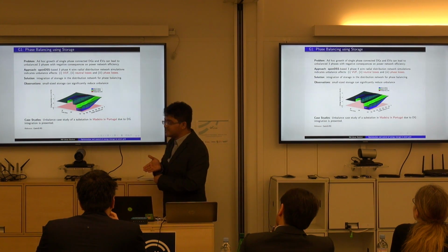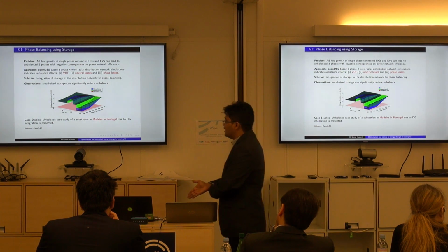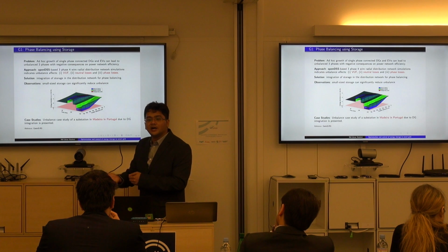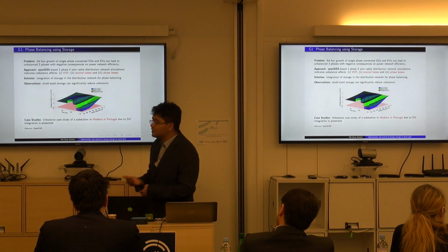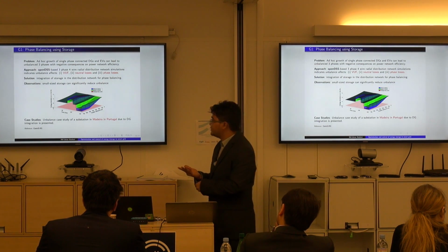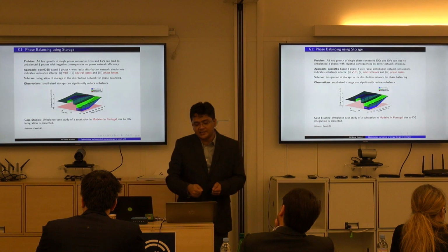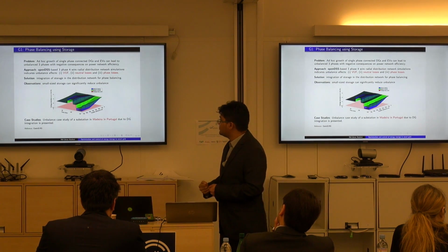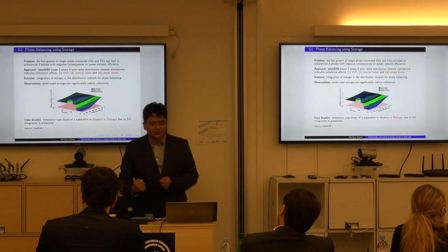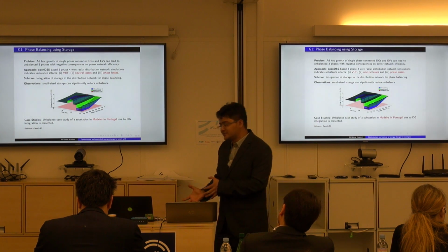What we see is that for a three-phase 4-wire radial distribution network, imbalance can cause the voltage unbalance factor to go above, say, 1 or 2%, which is the criterion. It can also increase losses in the neutral and in the phases. Now, the key idea is, can we use batteries, or in future maybe some form of flexibility, to solve this problem and create the balance? And if we can, what will be the size of the battery in such a case?